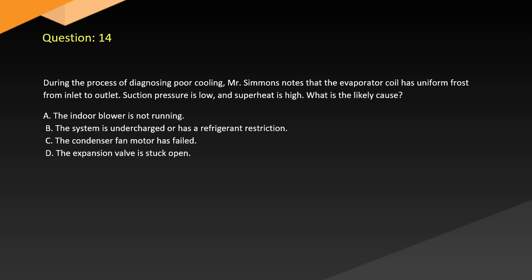Question 14. During the process of diagnosing poor cooling, Mr. Simmons notes that the evaporator coil has uniform frost from inlet to outlet. Suction pressure is low and superheat is high. What is the likely cause?